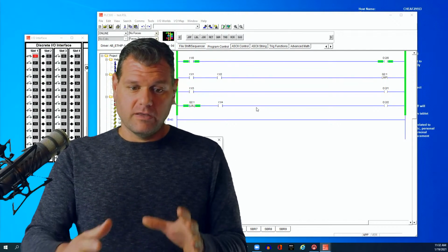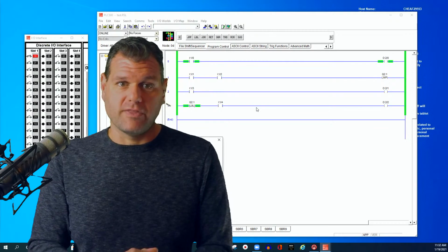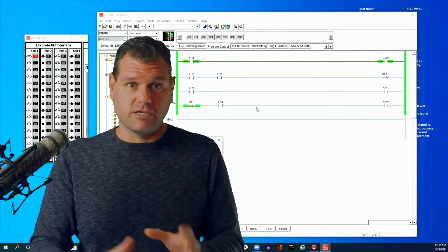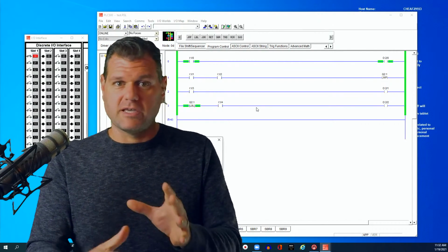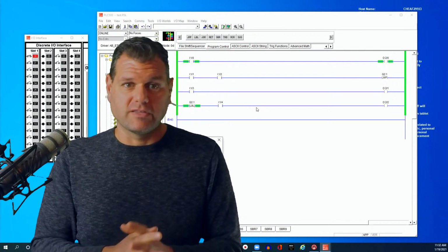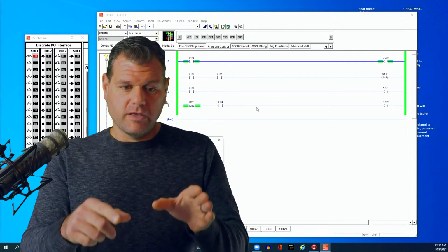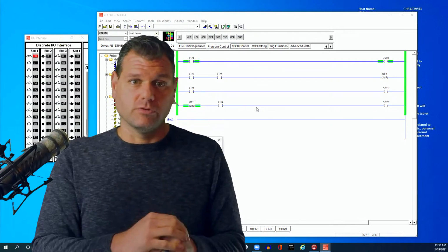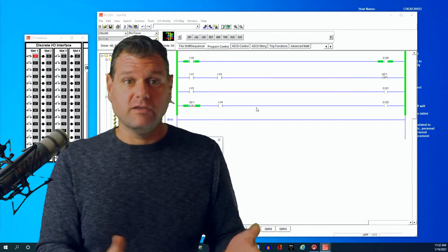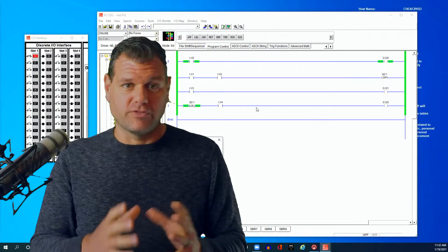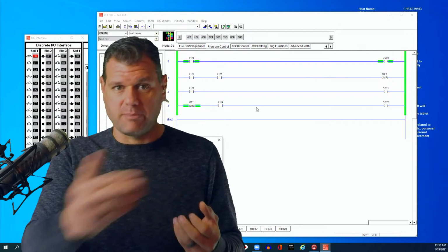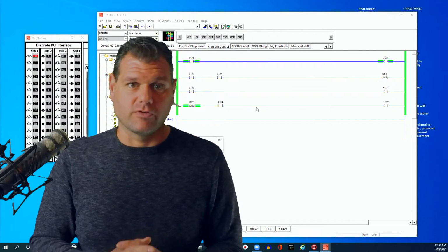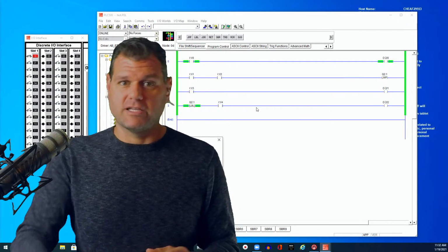And then, for whatever condition, let's say that you don't need to look at that code. Let's say you don't want to access or turn something on. You can jump right over that, and that's fine. If for some reason you needed to double back, you could tell it to jump back to, let's say, rung 19, and then you can have it scan again. So if the condition is now changed where it doesn't skip over that, you can have it run and scan over it. It's not necessary, but you could do that because it'll catch on the next rung.